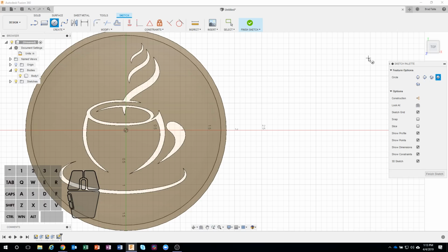Okay. So let's go ahead and do our center rectangle. Now I just have to get near this edge. You can kind of see how it's going to snap to it. And I'll just start to draw my rectangle. Now my width, I want to be precise. And right now it says 0.532. So I'm going to just say 0.5.